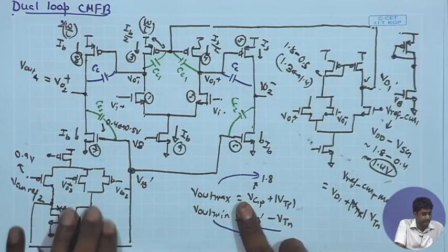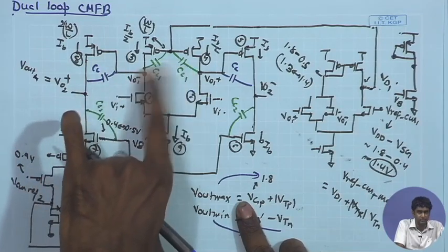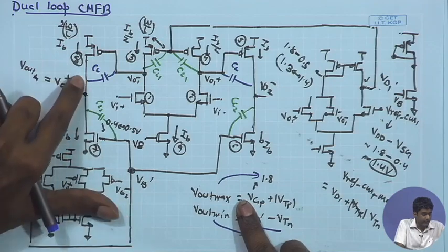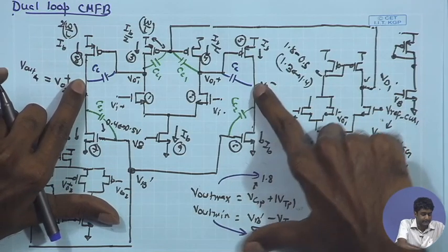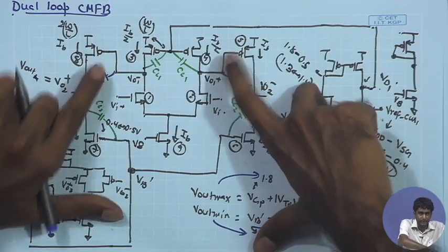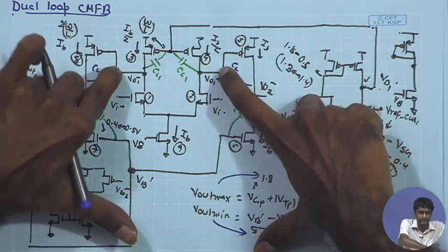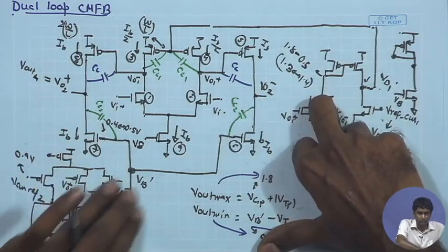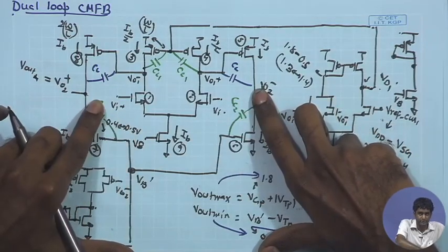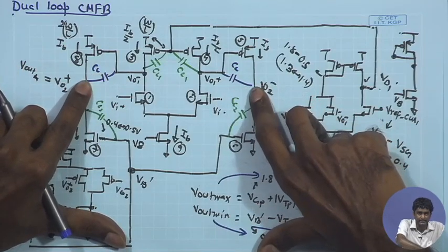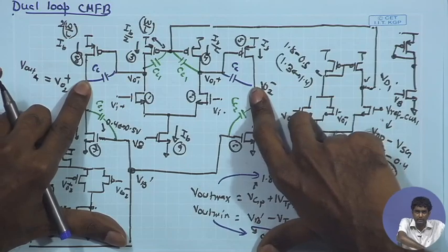So, while analyzing the second common mode feedback loop, we assume that these two DC points are fixed, and hence the gate voltage DC points are fixed, and as a result once again the CC for this stage also comes just as it is, right. So, from this point this is seen as an AC ground. So, while analyzing the second loop common mode feedback and taking the effect of CC2, the CC for the differential operation also comes between this point and AC ground. It is not going to have any multiplication as such.